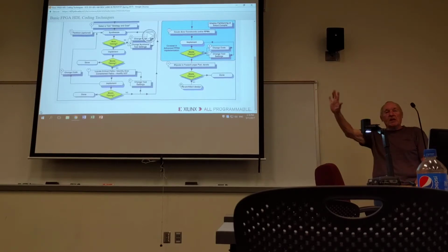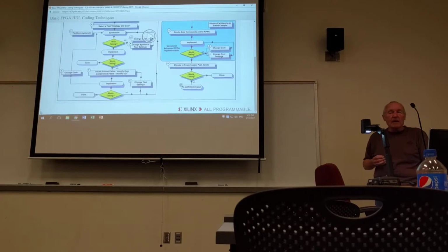First of all, you're not using LUTs and registers in the FPGA fabric. That leaves them available for other uses. The timing is precisely known for the hard IP, so you're going to get a much more accurate timing analysis done. And finally, the hard IP is considerably faster than what you could implement using LUTs and registers. So there are several advantages in using the hard IP.